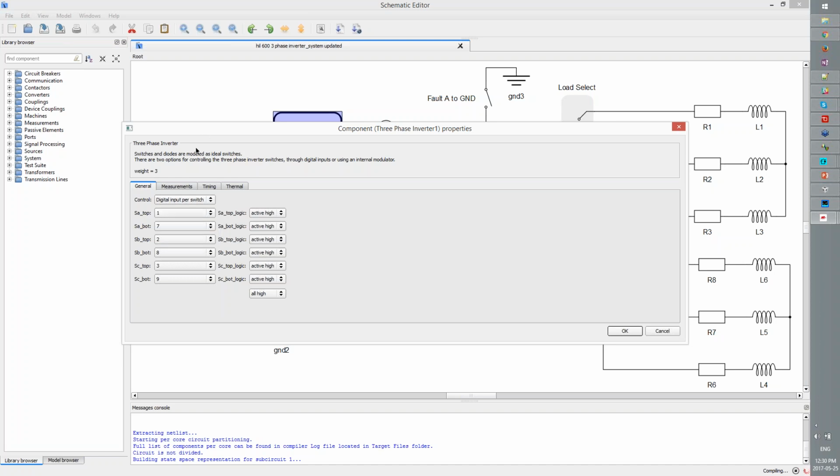The PWM outputs for timer 1 on this chip are the complementary pair that maps to digital inputs 1 and 7 on the HIL. Timer 2 on the DSP maps to pins 2 and 8 on the Typhoon HIL. And PWM timer 3 from the DSP maps to digital inputs 3 and 9 on the HIL. So that's why these are set up this way.